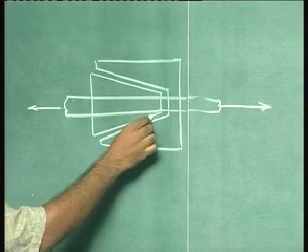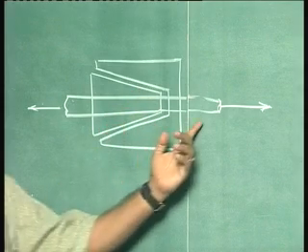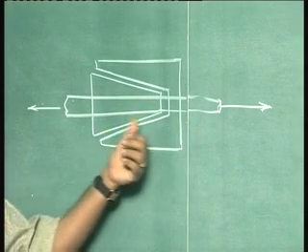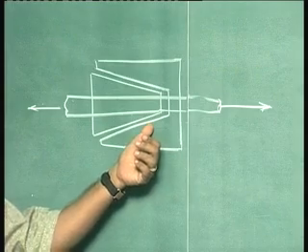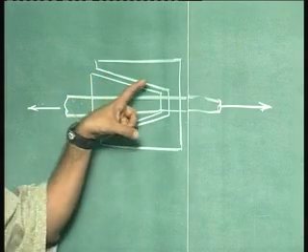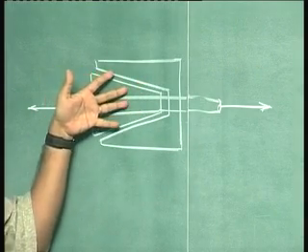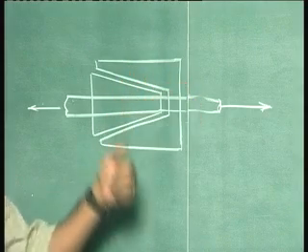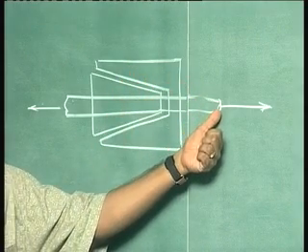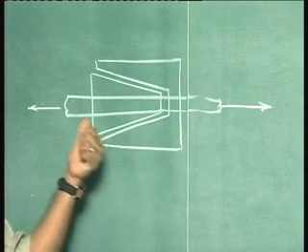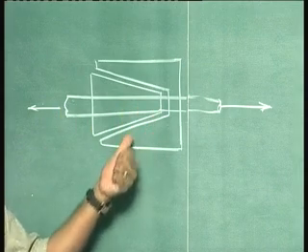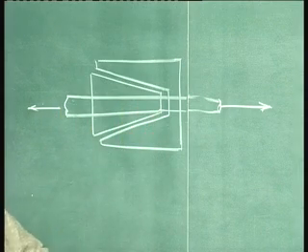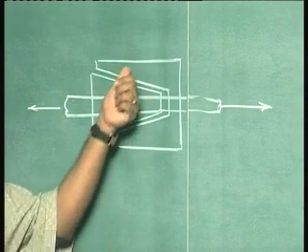When the wedge is being pulled by the tendon, it gradually sits in this block, and due to the friction action, the wedge is not able to move any further. Hence, the tension in the strands can be maintained by this wedge action, which acts on the principle of friction between these two blocks.